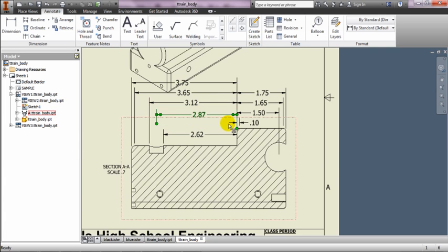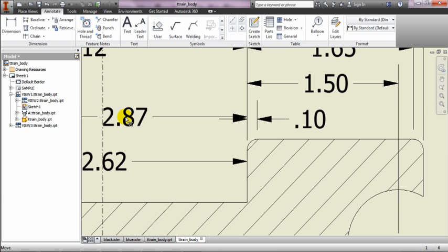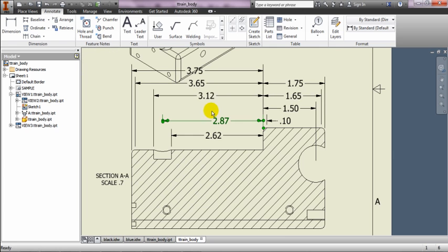And see this? See this arrow right here? I'm going to move this number so that the arrow is right on top of the other one right here. Yep, just like that. That's fine. Sharing the arrows is just fine. And stagger dimensions: if the numbers are right next to each other, you can stagger them so that you don't get confused.